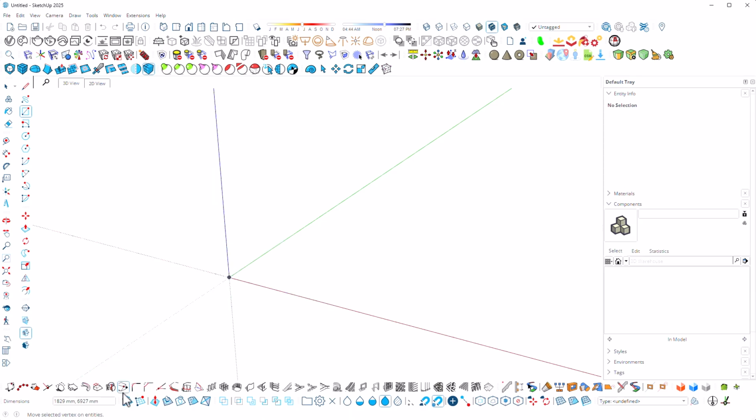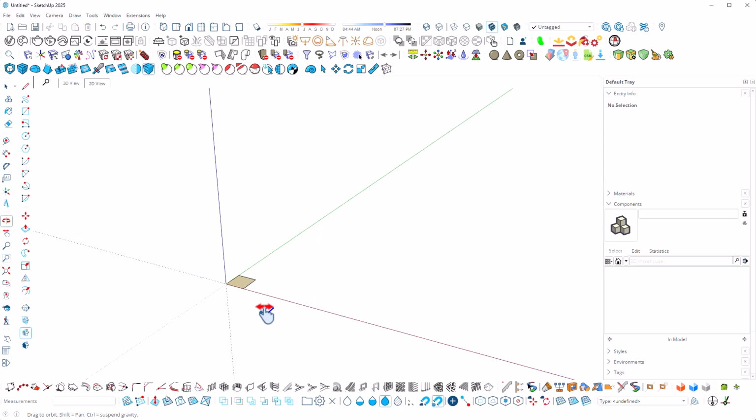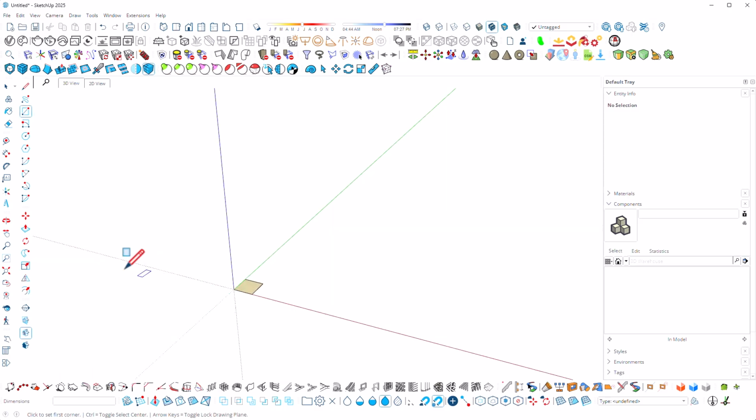The other thing to note is that in this little breakdown box we've got some dimensions, so we can use that to type in the dimensions of our pile, which are 125 mil by 125 mil. That'll give us a starting point, a little two-dimensional square which we can extrude. We'll extrude that using the push-pull tool. Hover over it, click, draw it up, and again you can use the keypad on your keyboard to enter 600, press enter, and that'll lift that 600.